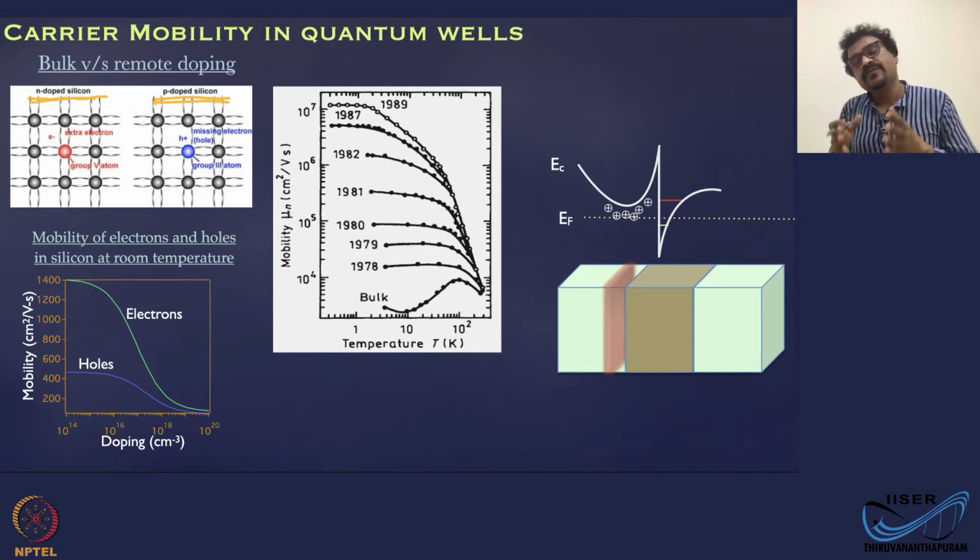So depending upon your application, if your aim is a really highly conducting material and you are not worried about mobility, then you can put in more dopants. But then you will not observe any quantum mechanical phenomena, because your mobility is very bad. You pump a lot of electrons into the system, but there are so many scattering events that observing quantum phenomena at any reasonable size scale is almost impossible.